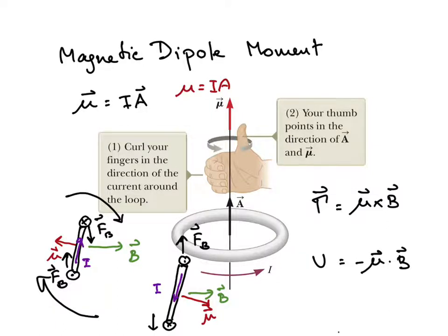And here it points in this direction, F_B. From this segment, you can see that if your forefinger points out, and the magnetic field points out of your palm, you have the magnetic force like this. Again, you can see that this magnetic force tries to rotate the plane into this direction.